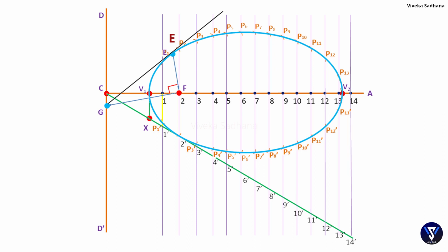to the curve. Mark the point TT' as the tangent to the curve, passing through the point E. Next, draw a line perpendicular to TT', passing through the point E. Mark it as the normal.